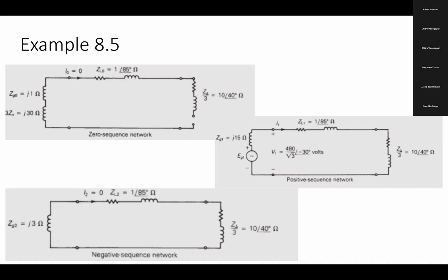The first current is coming from the positive sequence because that's the first network to which we connect the other networks. So the first current is always the highest current because it is coming out from the source undivided. Then negative and zero sequence are connected either in series with the positive or in parallel with the positive, so they carry lesser or the same current. If connected in parallel, then lesser current. So the peak of the negative sequence components will be lesser than the positive peak. The positive peak is called the highest peak, subtransient. The negative peak is called the transient, and then the zero sequence.